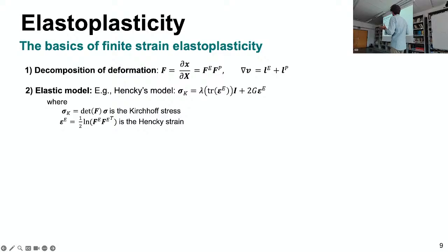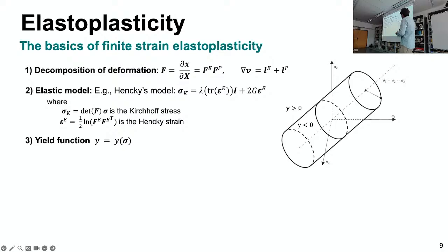For the elastic part, it's fine. You can choose your elastic model. Here, very typically, we are using Hencky's model. It's a very simple, hyperelastic, isotropic finite strain elastic model. It's basically the small strain relation that you know, but instead of having the Cauchy stress, you have the Kirchhoff stress. And instead of having just the small strain tensor, you have what's called the Hencky strain, so the logarithmic strain, if you will.